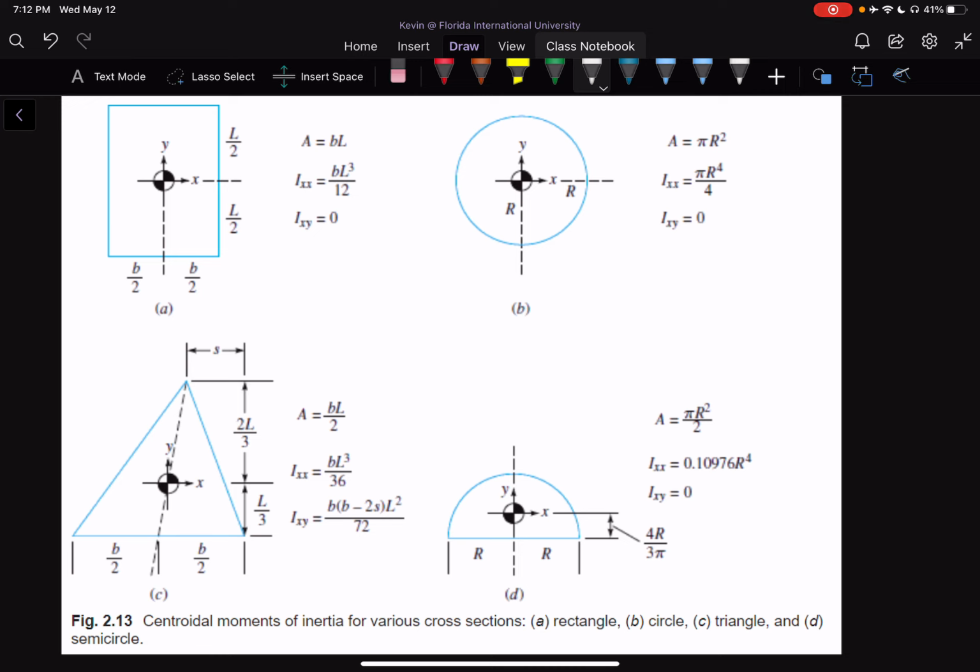Now, in our questions in the book, they're going to be telling us if we have to omit atmospheric pressure for these problems or not. In some problems, we'll omit atmospheric pressure because the plate is touching two atmospheric pressures and we can just omit it. In others, they will tell you to use atmospheric pressure, or they'll just tell you to use absolute pressure, or they won't say anything.